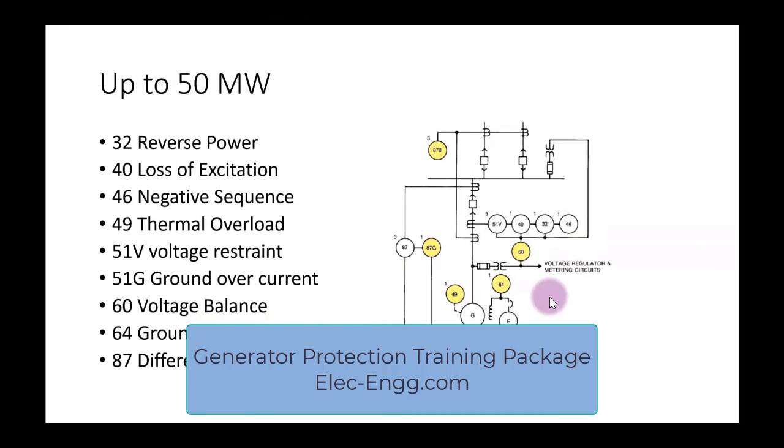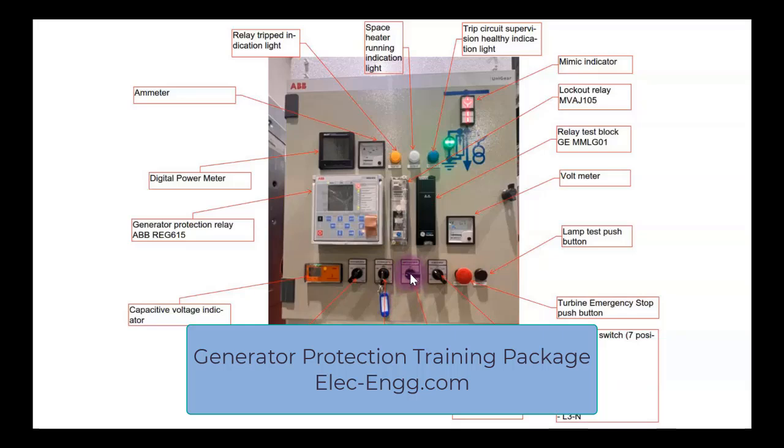I wanted to explain and mention that from these schemes we can understand which CTs or which PTs the protection function is connected to, and whether, for instance, the function requires voltage or current signals or both. Here we can see all of these functions require voltage and current signals, such as power, reverse power, and negative sequence, while negative sequence doesn't require a voltage signal, only the reverse power. Phase C, we can use this switch to switch between phase A, phase B, and phase C, or off.